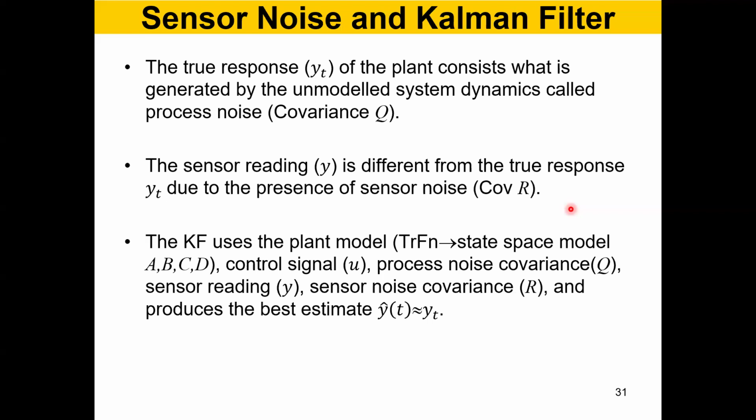So I think in this course, I'm not going to teach you Kalman filter. By the way, this is the standard Kalman filter, not the extended Kalman filter. But in your projects later, you will use mostly extended Kalman filter, right? The difference between the two: the standard Kalman filter is for linear systems, which can be represented by transfer functions, right? But if you don't have a transfer function, but you have a set of equations of your plant, and some equations are nonlinear, then you can use the nonlinear version, which is called the extended Kalman filter. In MATLAB, both options are available, right?